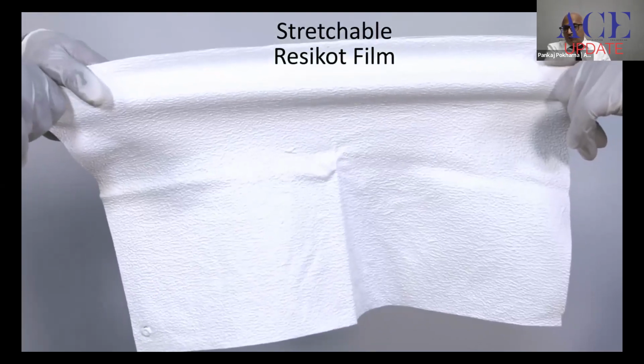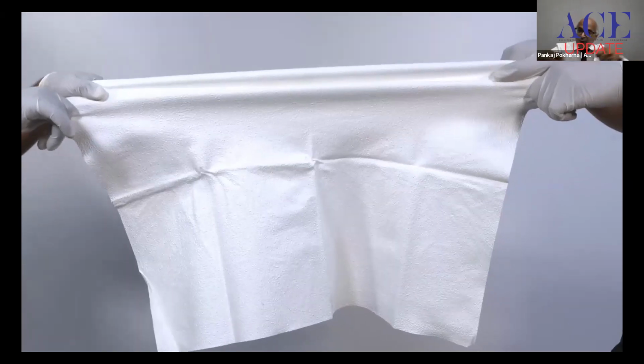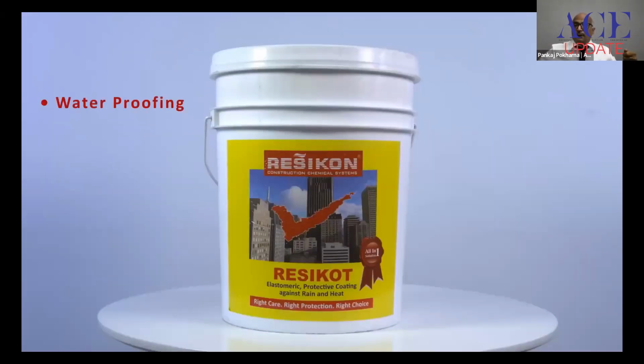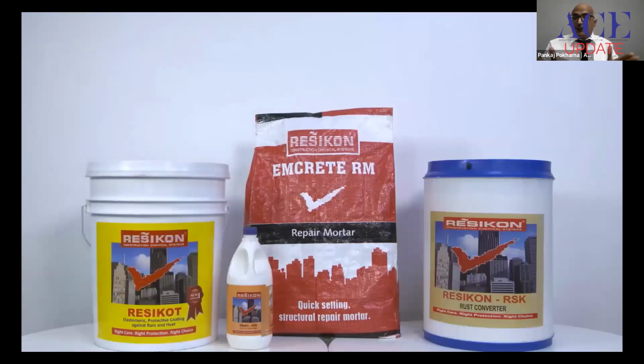Now when you take out the film, this is so elastomeric in nature, you can elongate it to more than 170%. So the product is waterproofing, it has crack bridging ability, easy to clean, it is also temperature resistant, UV resistant, and can be tinted to a color of your choice. This is the right choice for walls as well as terraces. And in the coming monsoons, this is the only solution which can act in a much better way.